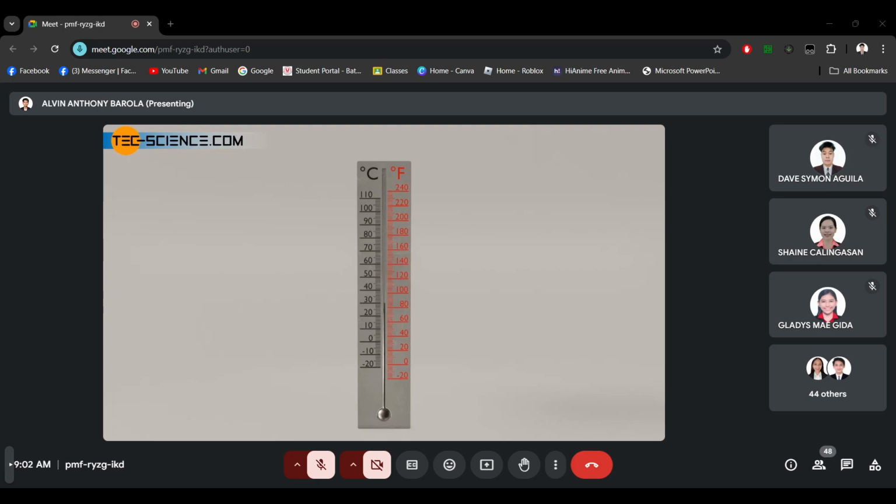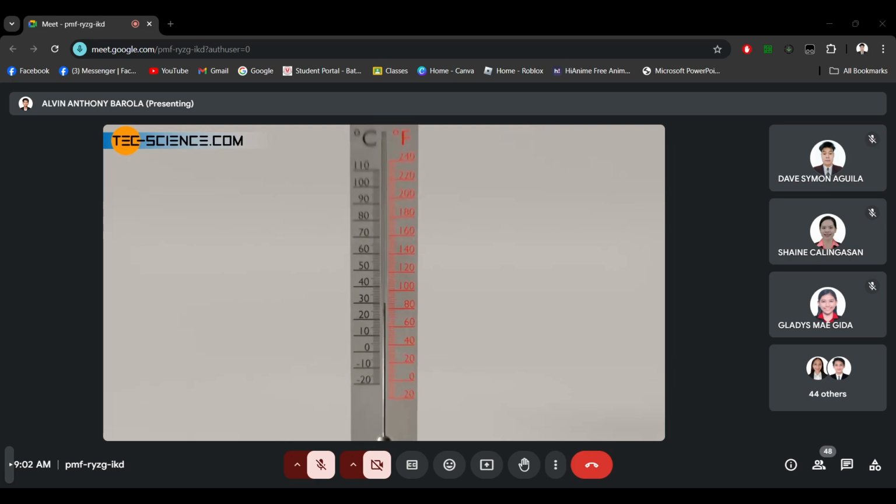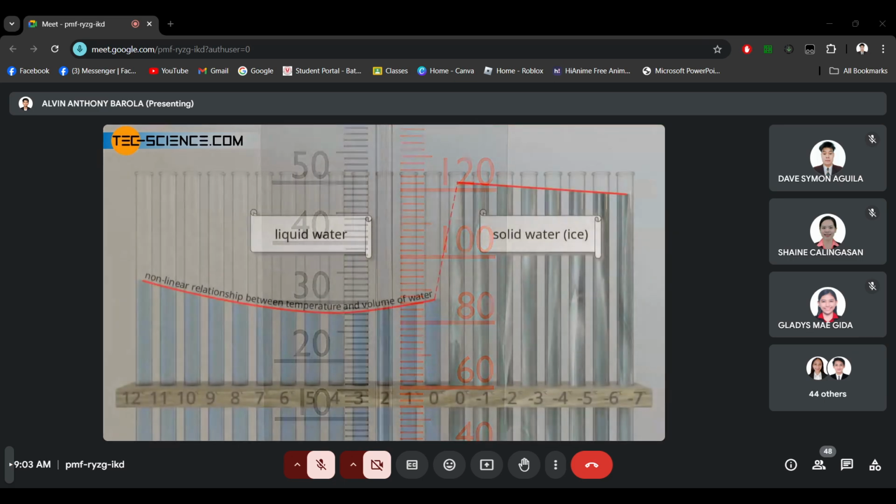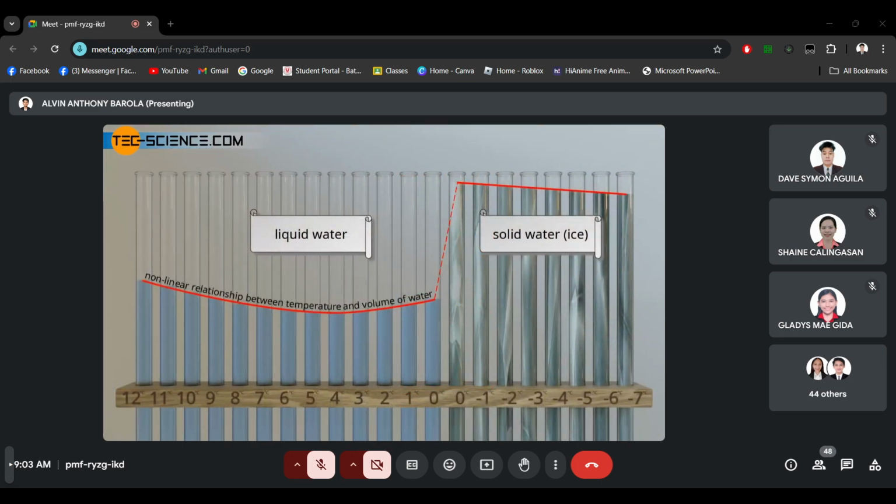Such thermometers are also called capillary thermometers. The liquids used in such thermometers must have certain properties in order to be suitable for use. For example, they must not freeze at low temperatures, which is why water, for example, is not suitable. The liquid should also have a sufficiently high boiling point so that they do not vaporize at high temperatures. Furthermore, the liquid must expand evenly with the temperature in the measuring range used. Otherwise, an uneven division of the scale on the thermometer would be necessary.